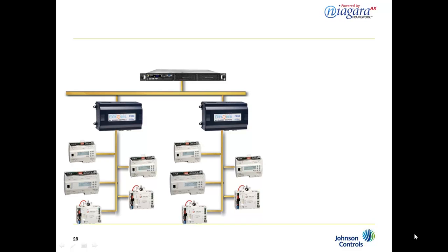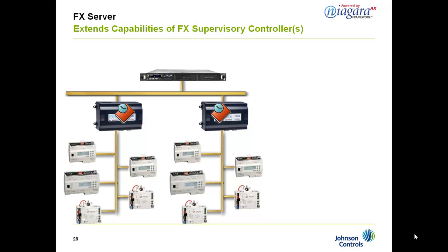The benefit of this is that it provides a consistent experience for programmers and operators. But the role of the FX Server is different than that of the FX supervisory controllers. FX Server is used to supervise one or more FX supervisory controllers and enhances their capabilities in the following ways. FX supervisory controllers can offload their stored alarms and histories to the FX Server for long-term archiving. FX Server can act as a master scheduler to coordinate the schedules of two or more FX supervisory controllers.